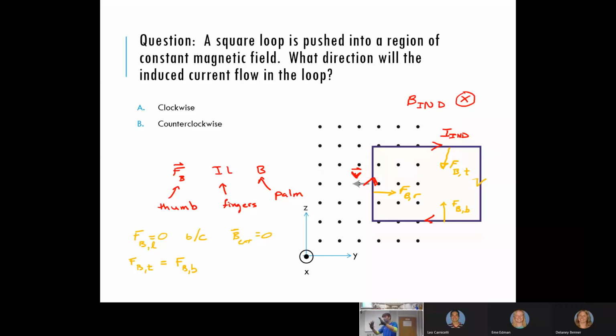And that's the part of the wheel that the brake pads press up against. So when you hit the brake pedal, there are brake pads in your brake assembly that press up against that rotor. That's how your car slows down. It's literally friction slowing your car down. That's literally all it is. It's the friction between the brake pads in your car and the rotor. Now, of course, brake pads wear out. Because of that mechanical contact, they heat up. They tend to rub a little bit of layer off every time you brake. And eventually, they'll wear out.